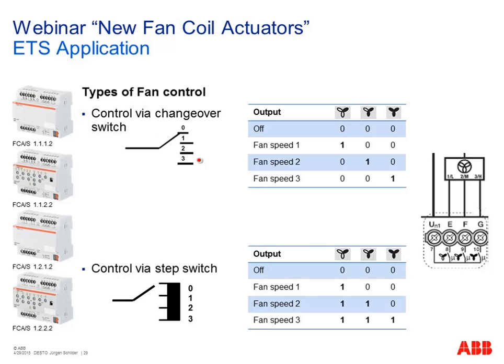Changeover switch, standard more or less, is also the default parameterization in the application of the fan coil actuators, but there's also something like this on the market. Fan speed control via step switch. The same principle for speed number 1, we have to close the first relay.